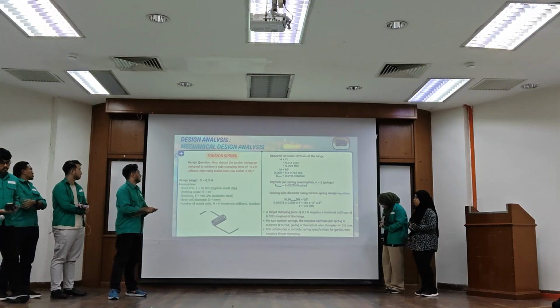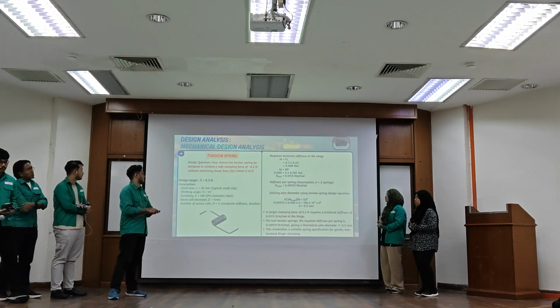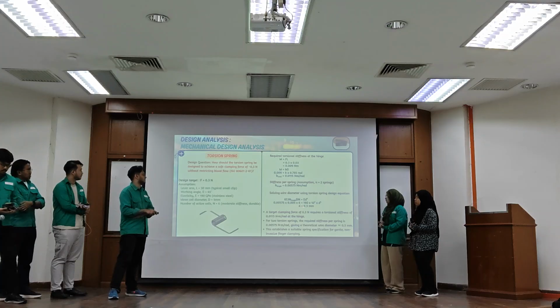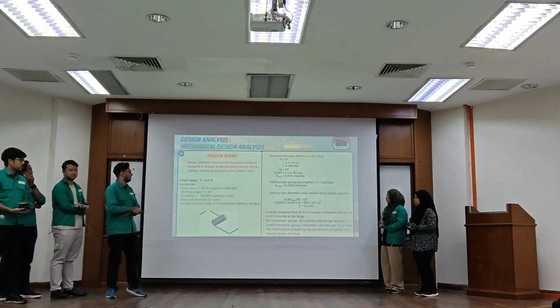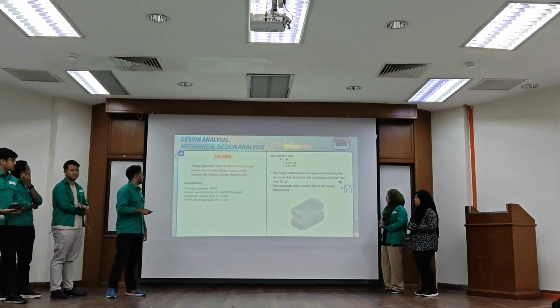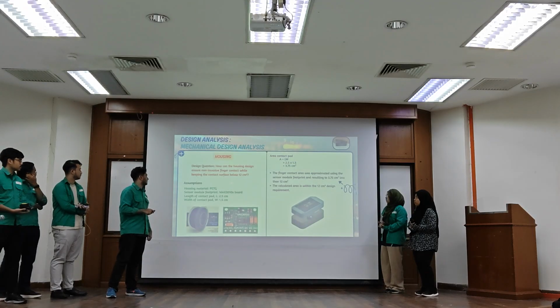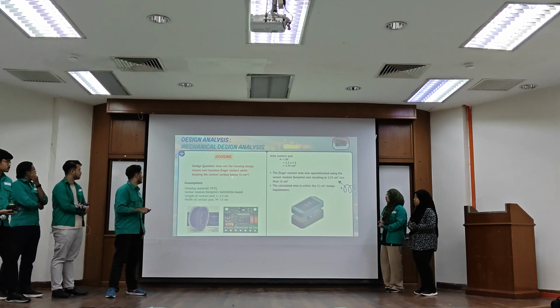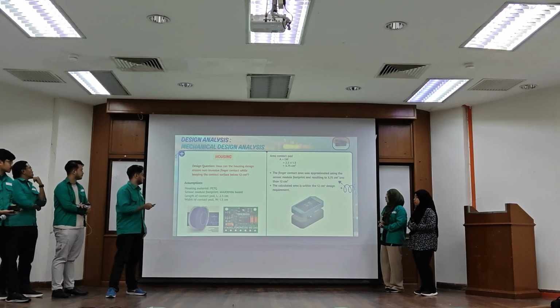So we start with 0.3 Newton force and end up with a spring that needs to be about 0.5 millimeter in diameter for the clamping. Next is the housing, where we target a contact surface below 12 centimeters square, and we achieve that.